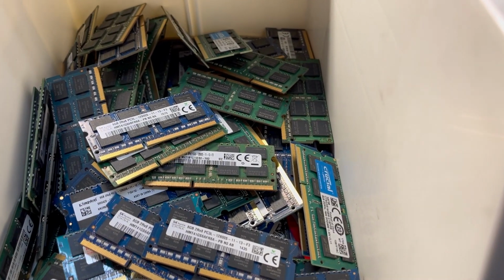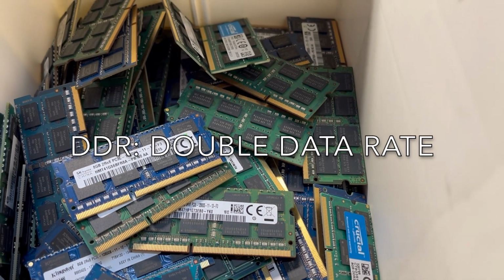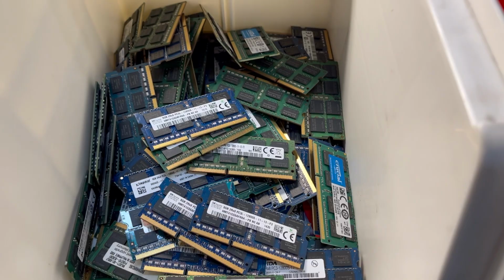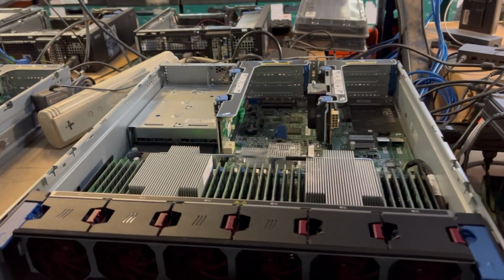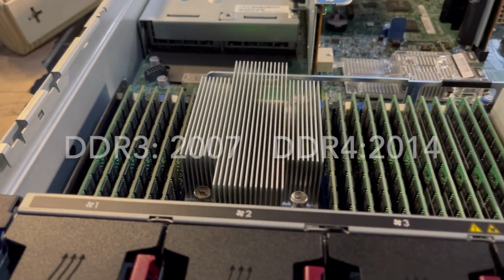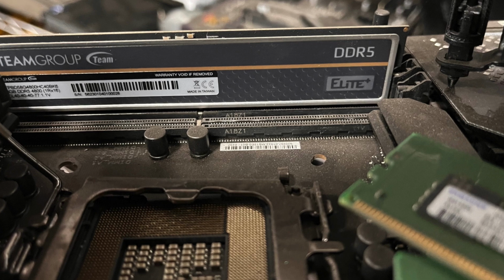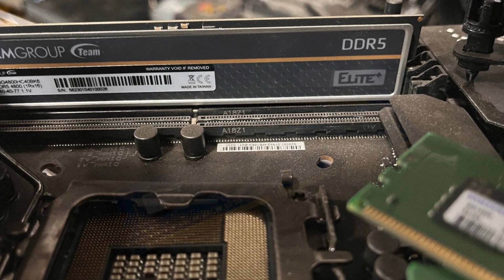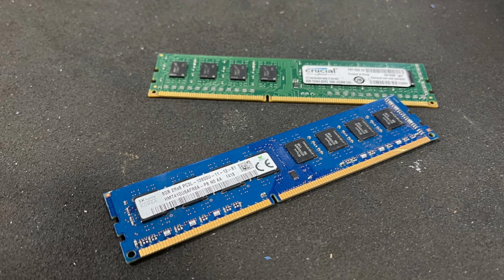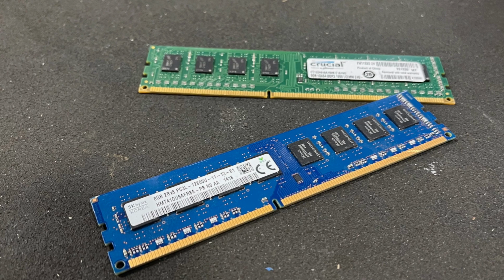RAM is sorted by generation. DDR stands for double data rate, and the earliest generations, DDR1 and 2, are no longer in use and are not commonly tested. DDR3 came out in 2007 and DDR4 in 2014, and both are still in use. The latest generation is DDR5. Different generations of RAM have a different number of gold connectors along the bottom edge, so RAM needs to be tested on devices compatible with the RAM module itself.